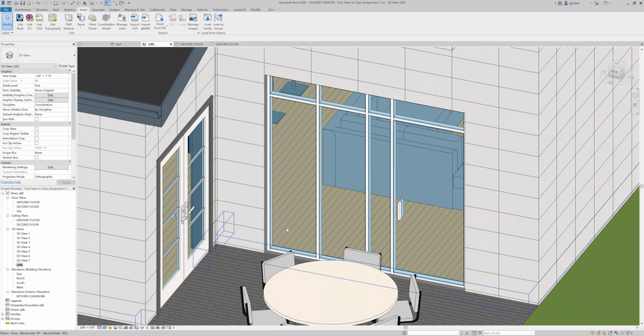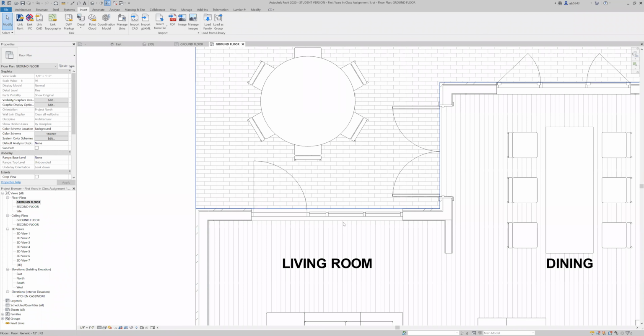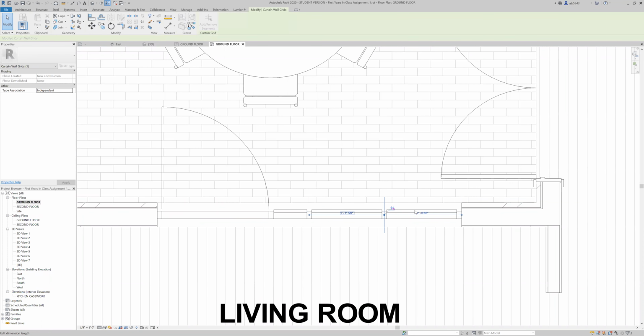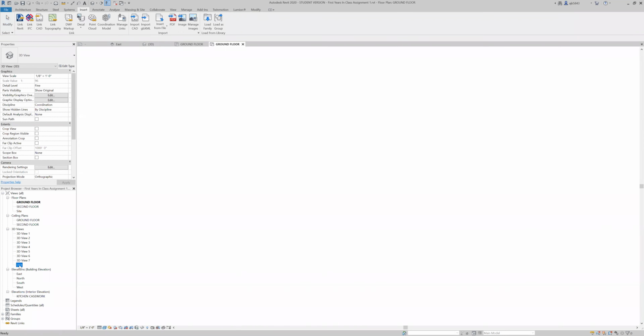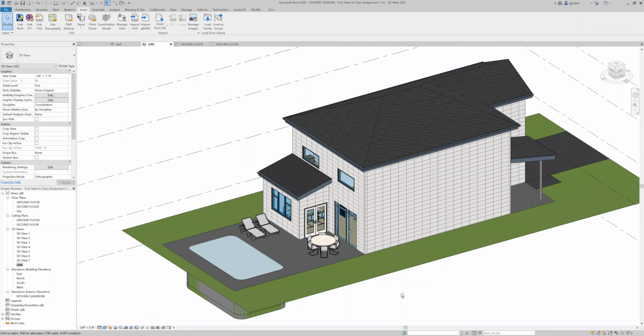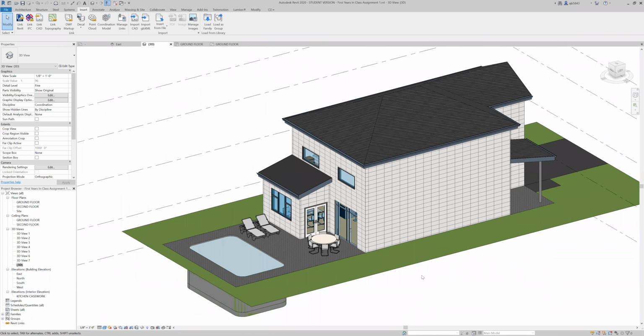And if we want to clean this up a little bit, you could go ahead and adjust the remaining grids. You could set these to some sort of fixed distance, whether it's 1'-3" or however you'd like for your design, just to clean that up a little bit after you place your door in.